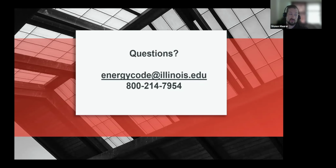But as far as the Manual J goes, if you're adding an addition to a building, you're still going to model the whole building. Try not to confuse the Manual J, where you're sizing the equipment, with code compliance, which are two separate topics. Unless, for instance, you had a mini split for that addition and it wasn't serving the rest of the house. Yeah, if you were adding on a space that had its own piece of equipment, you could model that space individually. And then Jennifer says, if an addition is proposed for use with existing equipment and modified extended ductwork, where is the requirement for Manual J?